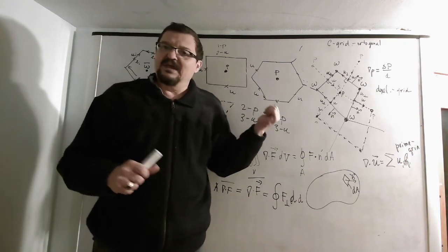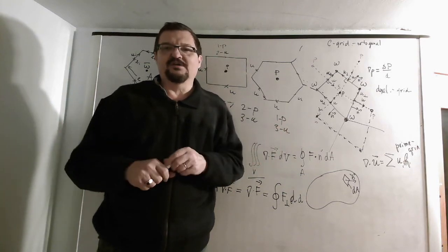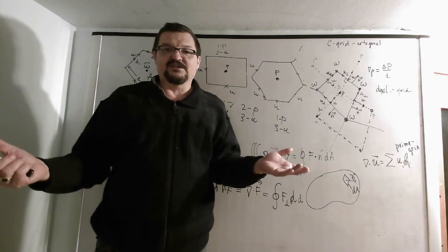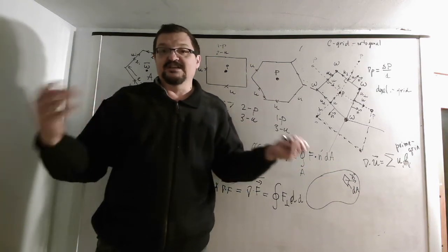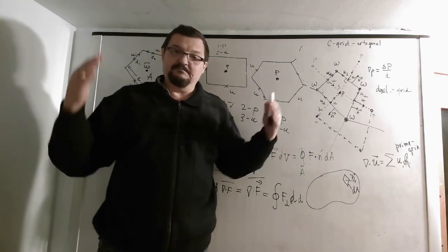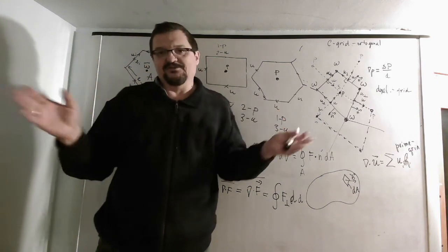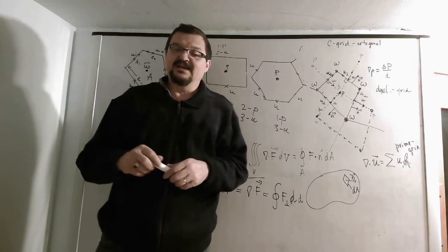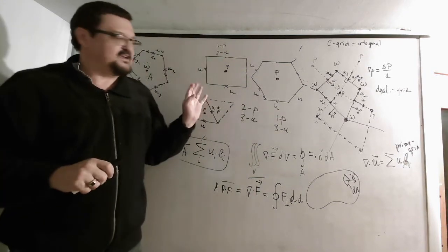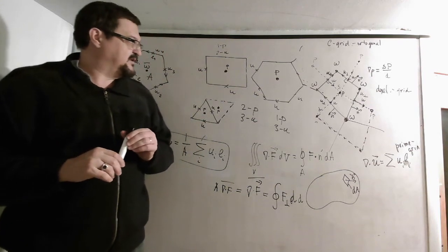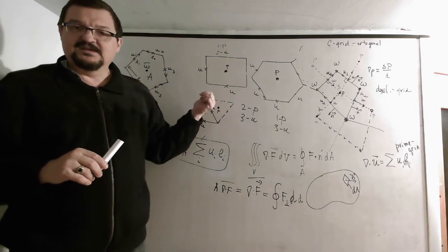So you're basically wasting your computer resources by effectively running on a coarser grid than you actually allocated. You allocated a very dense, very high resolution grid, but in reality you're running at coarse resolution because you use these filters. So that's a little comment that I wanted to make about these computational modes in space.